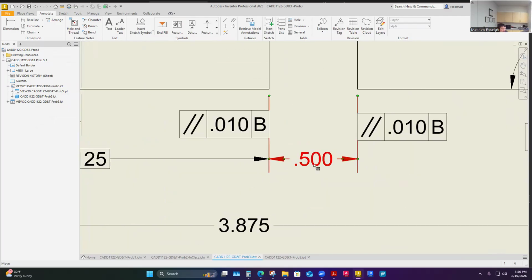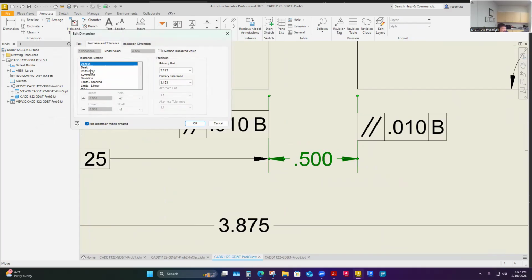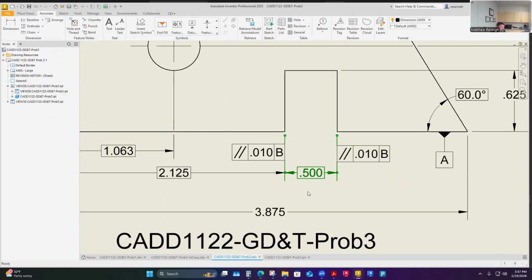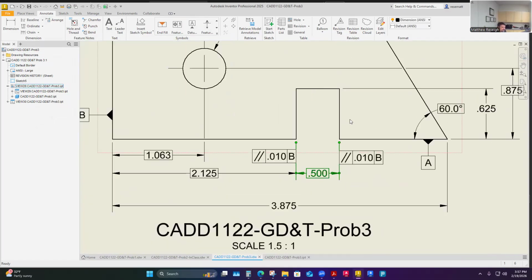And I think I will say that I'll just put this one as a basic dimension then. And then I've got the relationship that we've seen with locating holes and center to center of holes or something. So if I make these both basic, then I think that will work. They're both locating dimensions. And this one's almost double-duty as a size. And then I've got this other surface of that feature that I need to locate.